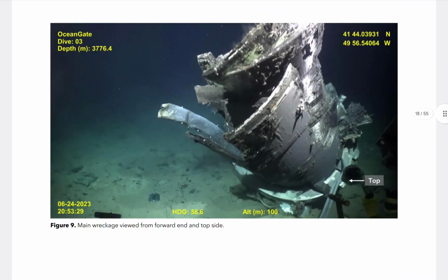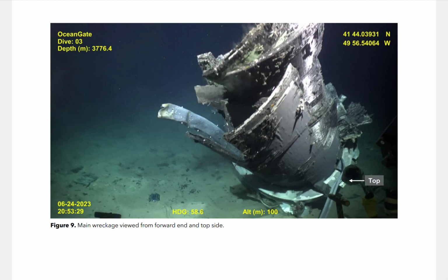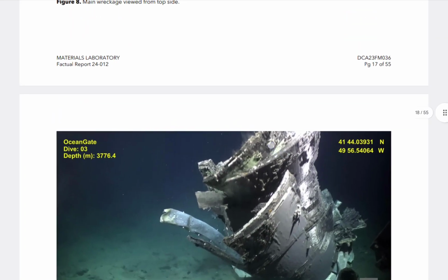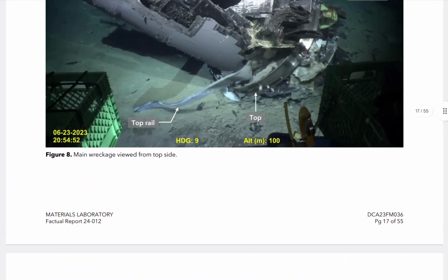Now, the part tying into the outer part here, this is all buckling. All right. There's a carbon fiber. This is the part that I said came off, rotated, however you like to think of it, rotating in the direction I showed you, and pulling itself off of there. And that's why this isn't buckled here, and why the other end is also not buckled, why it's sheared off, because again, the pressure is changed, pressure differential.